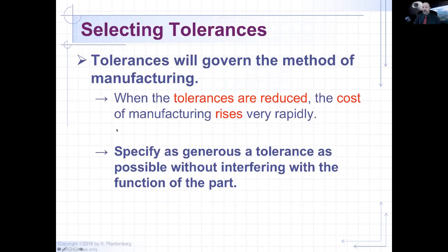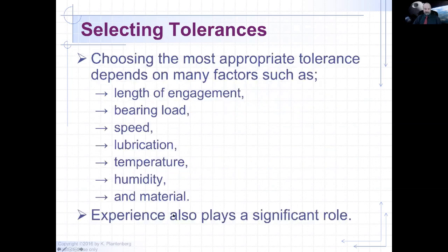Okay, always remember that when you make things higher toleranced, it's harder to make and it costs more money. So as an engineer and a designer, you want to try to keep the tolerances as loose as you can and still have the part function as intended.